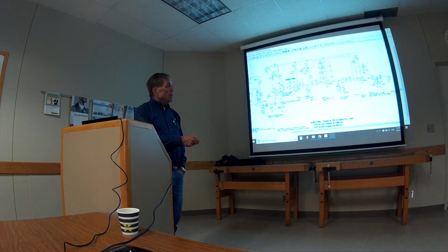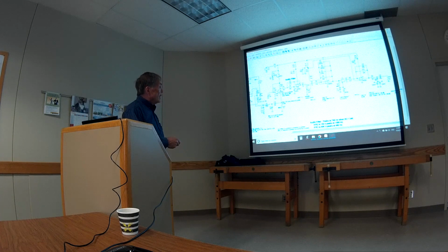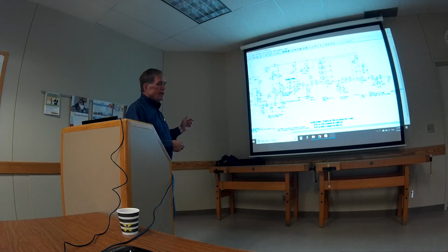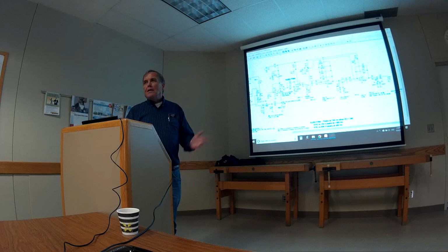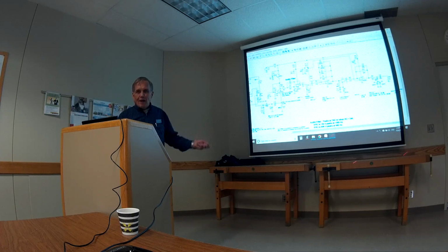And then of course there's just a little ear protection out here with some Schottky diodes so the signal would be clamped if it gets too big. But anyway, I did all these calculations. You could add up the gains, or you could add the partials. And it says I get 104 dB of gain, right? Well, I went home and measured mine. I injected the signal in here, and I measured 105 dB on the output. It was very reassuring to see that the math works, and the values that I had selected were going to give me pretty close to what I have.